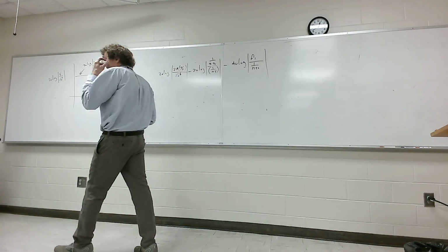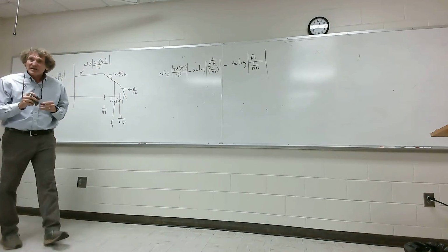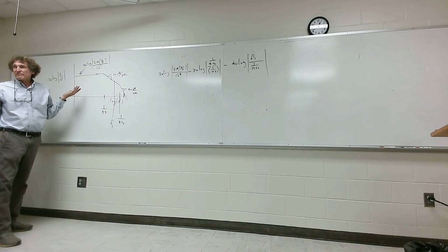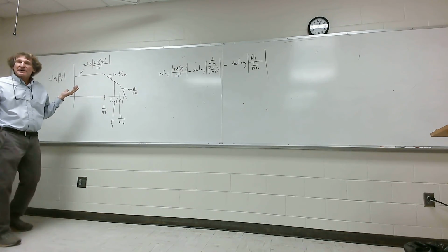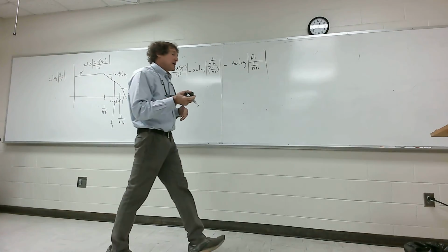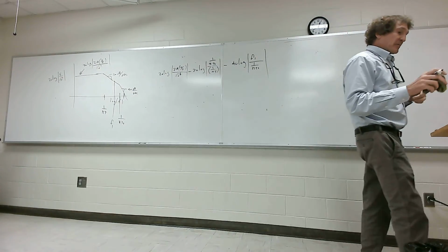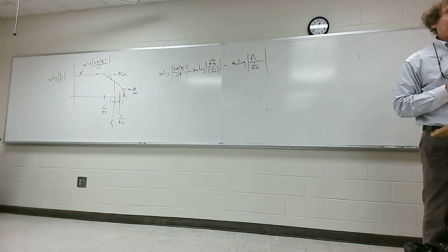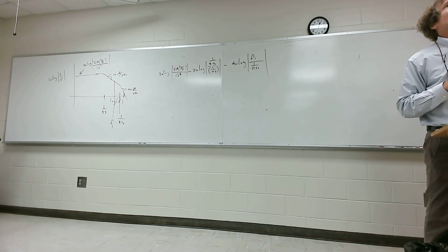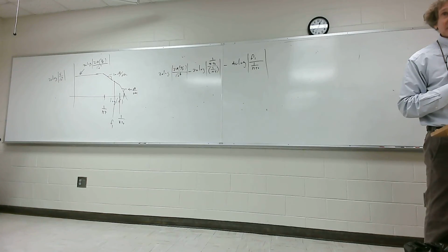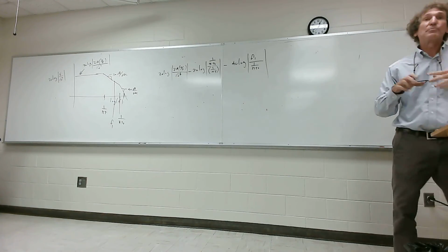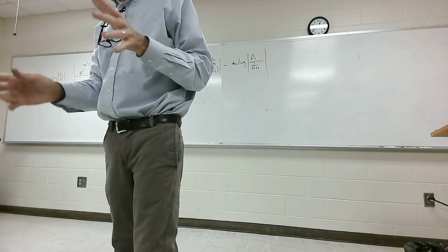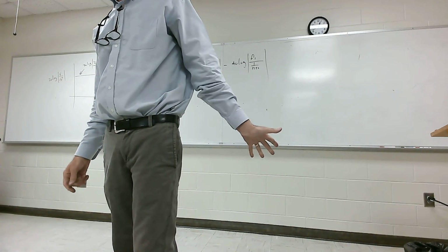But this is really MC. And this is why bandwidth and a lot of things like that don't really have a clear meaning. I mean, where's the bandwidth on that? A lot of times we have to know the type of problem you're dealing with. This is really MC, and we'll talk about it. It's not just 1 over tau rise, I'll tell you that. He says it's 0.5 over tau rise. That's hand waving in his book, Dr. Winston. He's trying to give you an estimate, but it's a very coarse estimate.